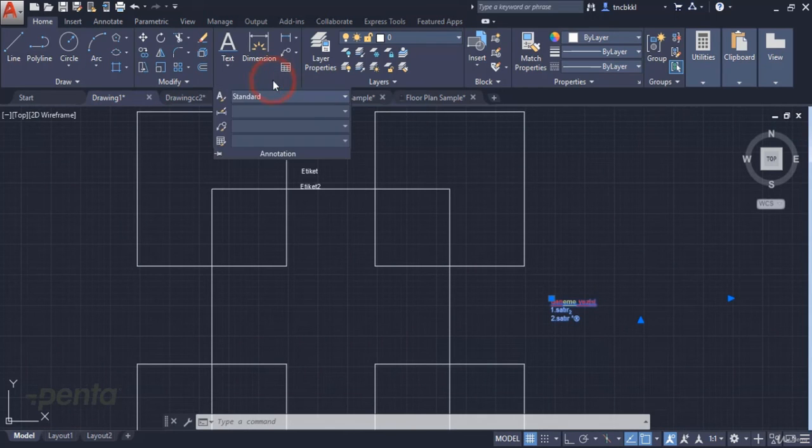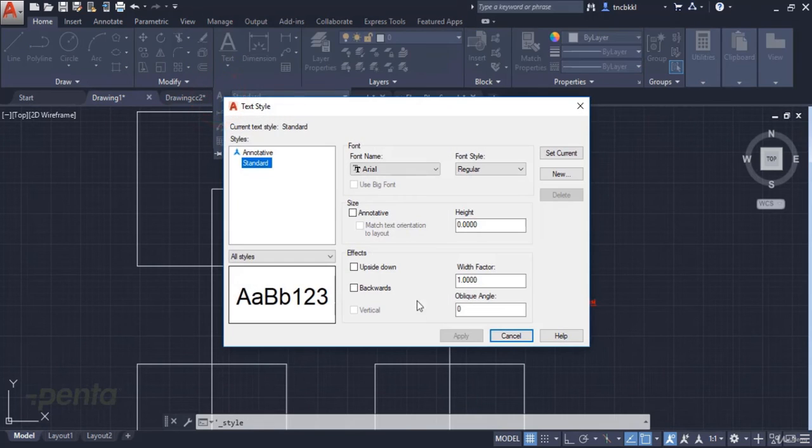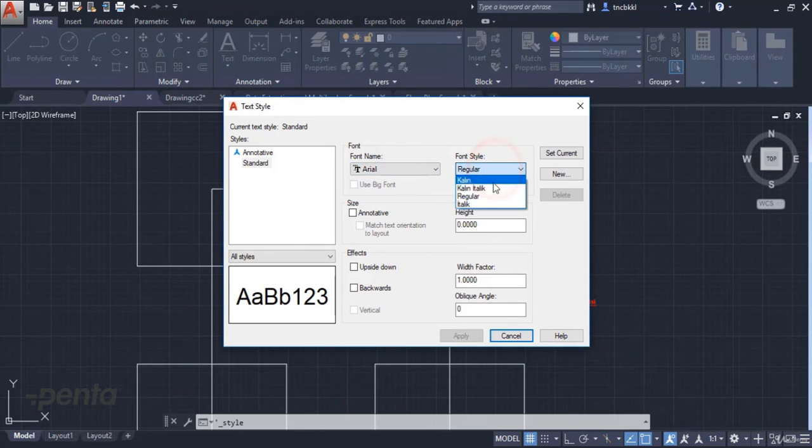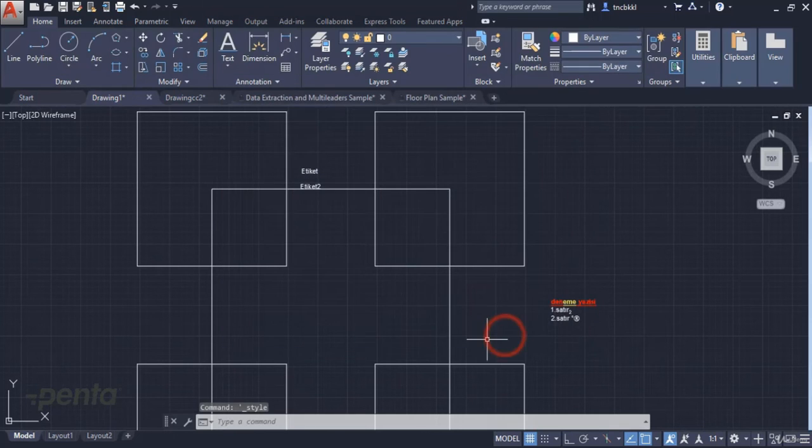Finally, we have a panel where we can edit the text types on our screen. Here, we access the text style menu to change certain settings. As you can see here, the standard font, font style, and height can be changed using this menu. We press apply after making our changes, and we can customize the standard fonts we use. Of course, when we come up to the multiline part, we can set unique fonts for ourselves and make changes here as well.